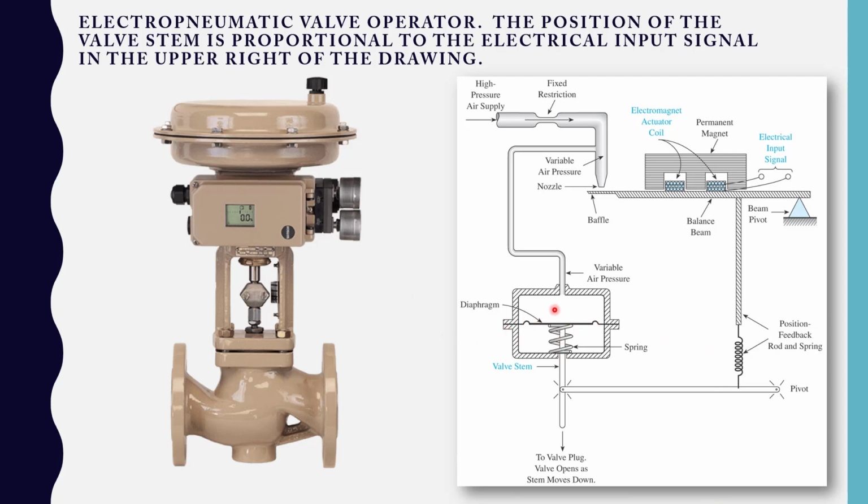Here's the diaphragm of this valve. It's located up in here, and this is the actual passageway. So this stem that we're seeing right here is this piece right here. So here's my inlet, here's my outlet. The valve's situated here. This pulls it up or lowers it down. And it's variable. It's not a snap action on-off controller. It's proportional.